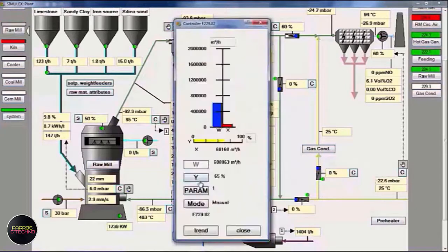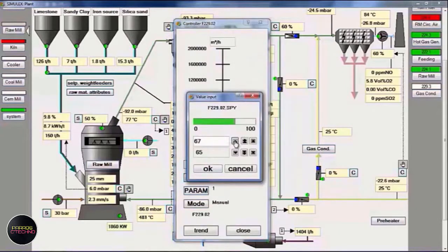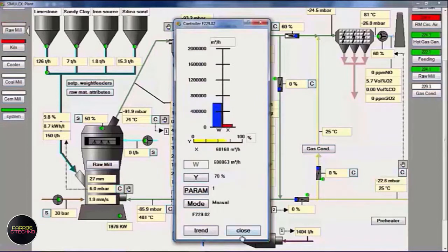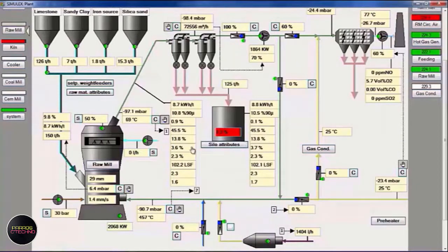Even though this is just a simulation, we can use it to operate the mill, so that at least a standard operation is made. So, to run this raw mill for the first time, what are the preparations? Later we can also do troubleshooting in this simulation, such as why the mill vibrates and there are other disturbances, or why the percent LSF is so high it can't match the standard, and so on. Various kinds of trouble can be simulated and will not damage the equipment, because this simulation is not directly connected to the factory.